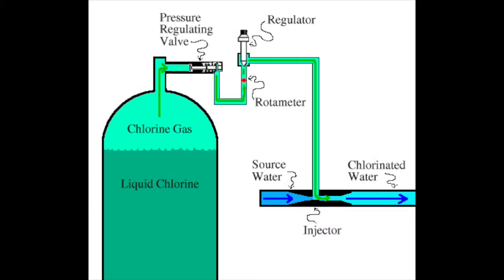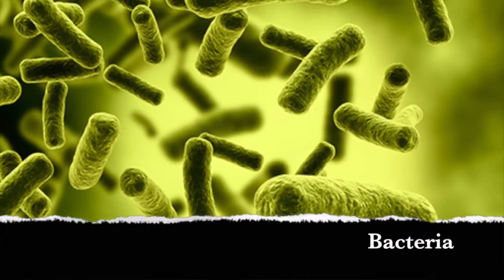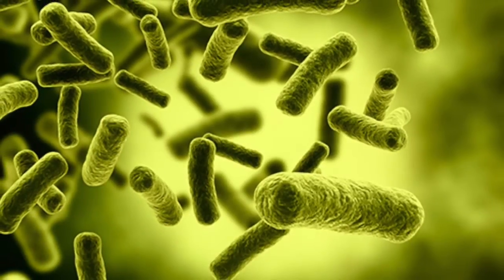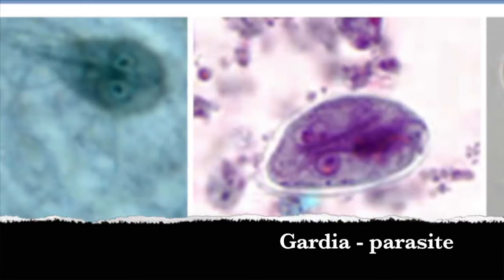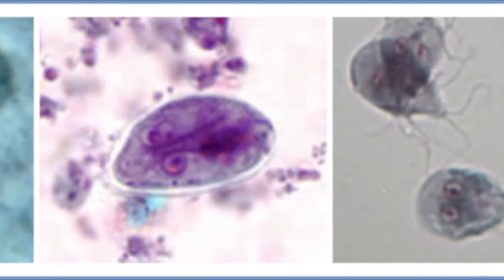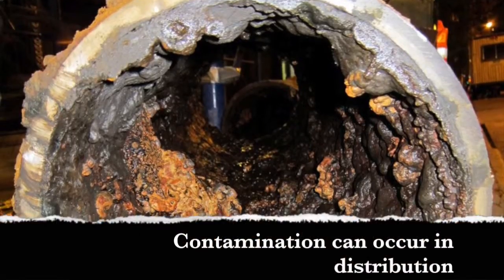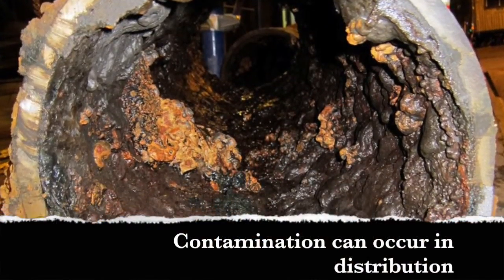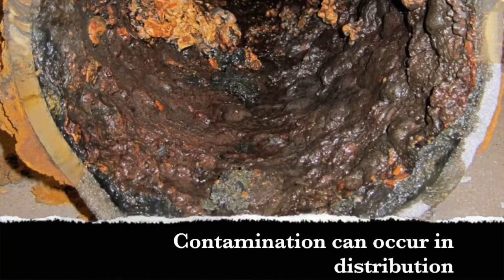Disinfection. Water is disinfected before it enters the distribution system to ensure any disease-causing bacteria, viruses, and parasites are destroyed, and to help stop them reforming while the water is in the distribution pipes. Chlorine is used because it's a very effective disinfectant, and residual concentrations can be maintained to guard against possible biological contamination in the water distribution system. If water needs to travel a long distance in the pipes, ammonia may also be added.